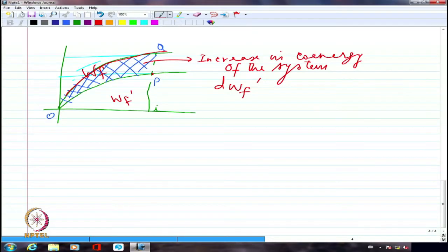The two together, actually, I am getting the electrical energy input. That's all I am saying. So my electrical energy input is going towards, rather I should say, three tasks. One is resistance loss. Definitely there will be resistance loss whether I like it or not. The second task is to increase the field energy. Apart from that, whatever is left over goes towards mechanical energy conversion. Alone. That was because the movement was zero.